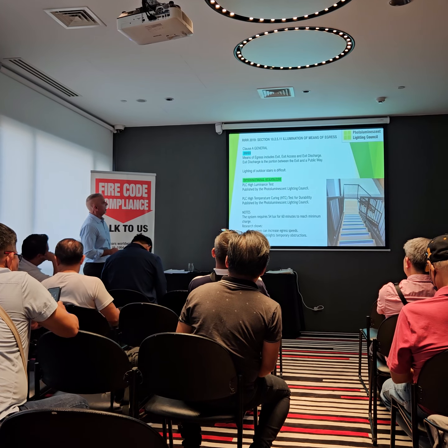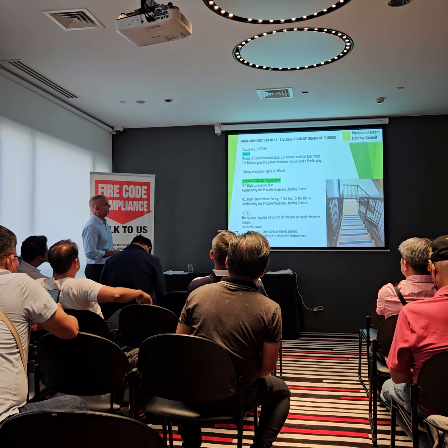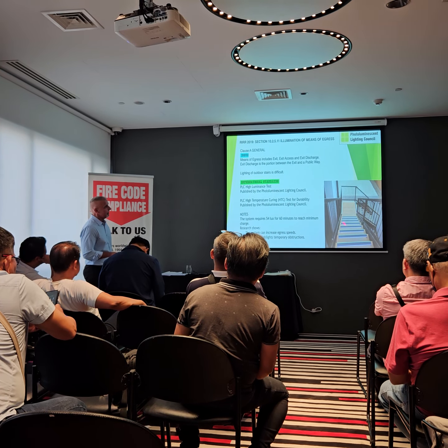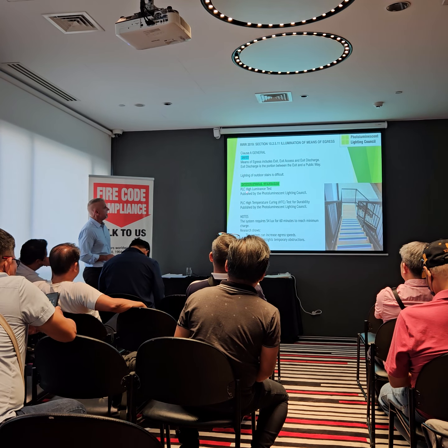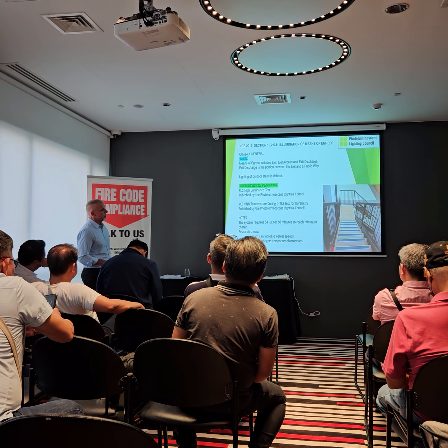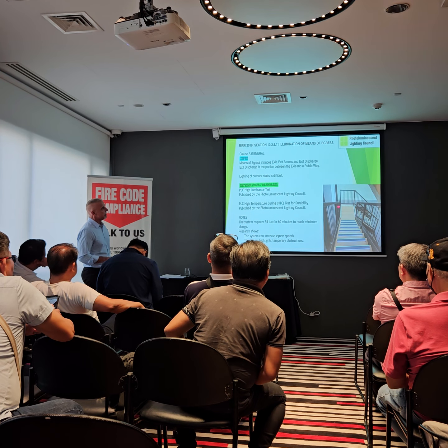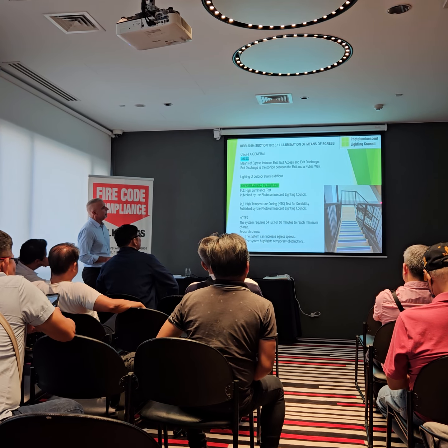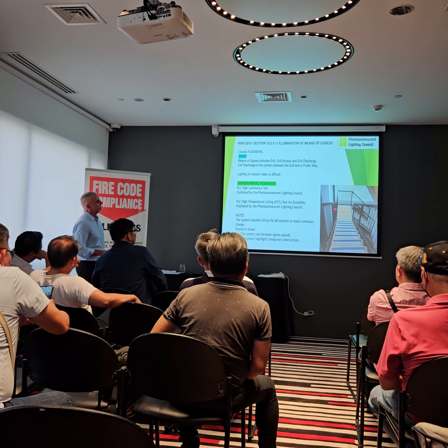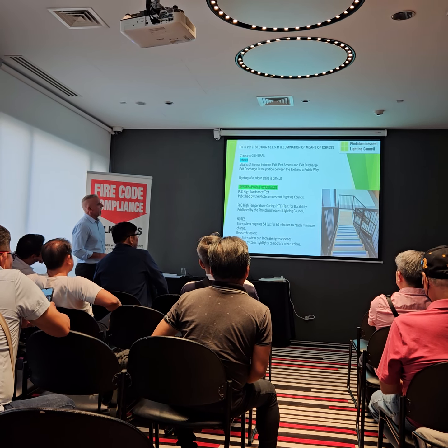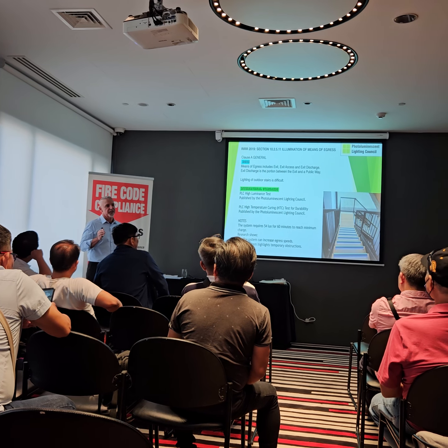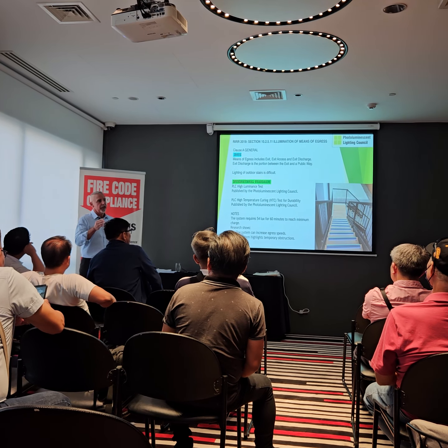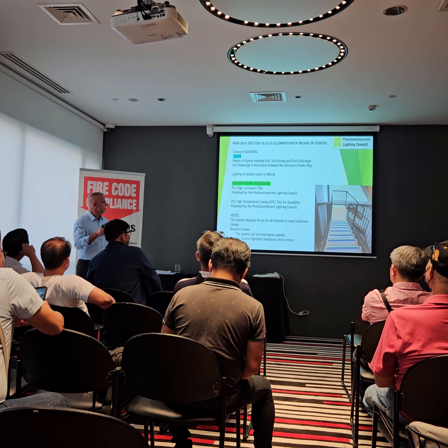So this is where we have proposed, if it's an outdoor stair like that, use the PLC high luminance test and put material on the edge of steps. Can't quite see it there, but it's on the handrails and on the landings. And if it's getting daylight, and remember it doesn't need to be direct sunlight, it will be visible all night.